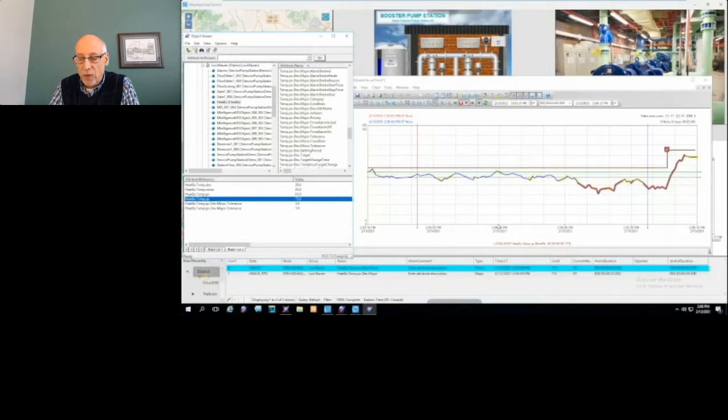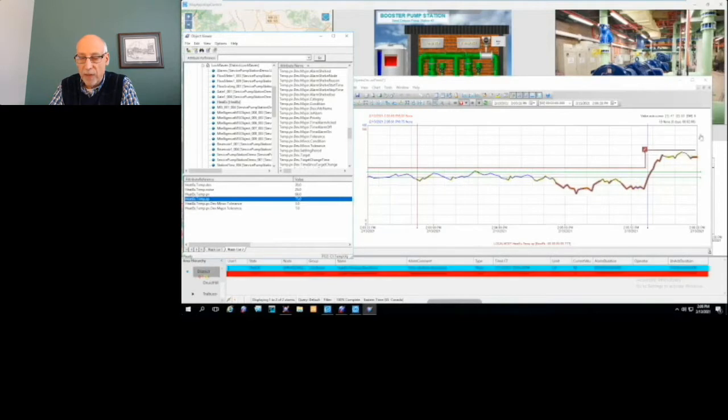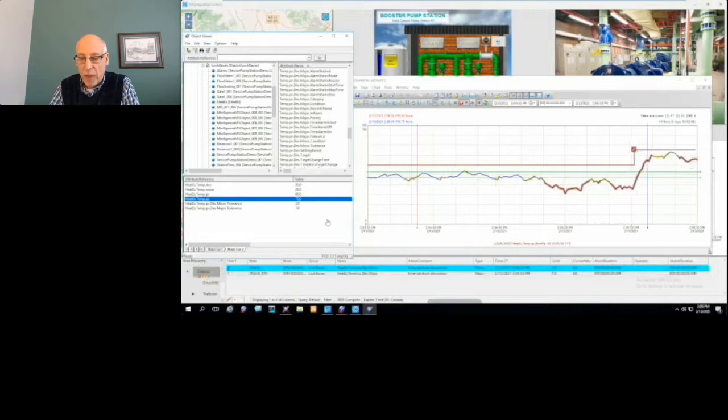So you can see it's a great tool to be able to determine if I start skewing out of control from my actual process variables. And again, that script behind the scenes is changing that set point based on what the operator changes. So I don't have to go back in the IDE and change that if I'm making a set point change.